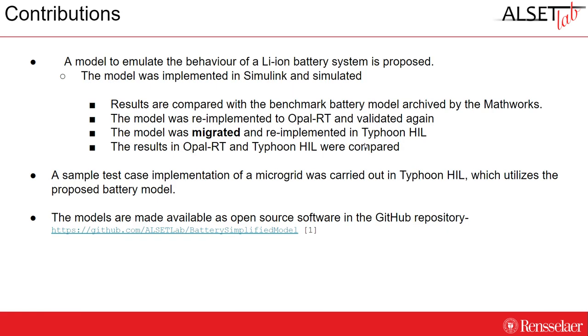So, these are the contributions of our work. We proposed a simple battery model. We implemented it in Simulink and compared the results with the archived benchmark battery model. Then we took our model to Opal-RT, that's the real-time implementation of the MATLAB model, and then we compared those results with the real-time simulation results of the benchmark model too.